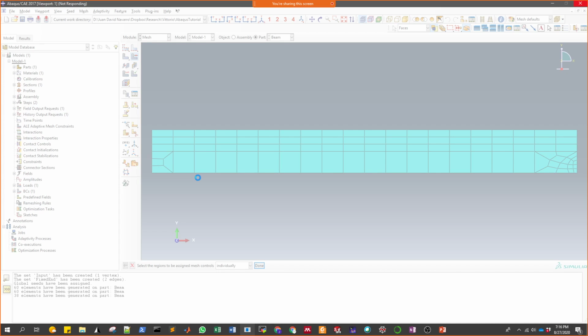Of course, if you use a higher order, you might have more approximation, but there are problems of using higher orders. For example, if you have wave propagation problems, then there are spurious effects. And the thing is, by using higher order elements, you will be inducing numerical errors. So you have to be careful on which kind of element you use.